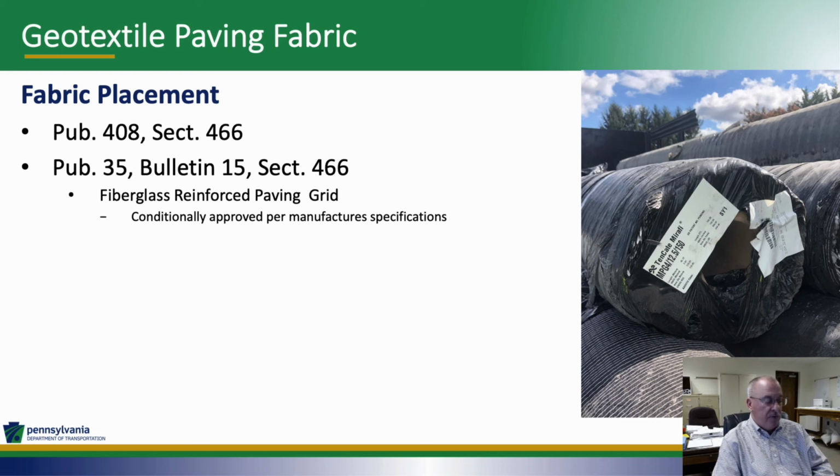You need to use caution when placing your Superpave material so that the temperatures do not exceed 350 degrees, because you don't want to damage the geotextile paving fabric when you're placing the bituminous product. You'll notice in the following video that the contractor applied the asphalt material only as far in advance of the geotextile paving fabric installation as is appropriate to ensure a tacky surface at the time of geotextile paving fabric placement.